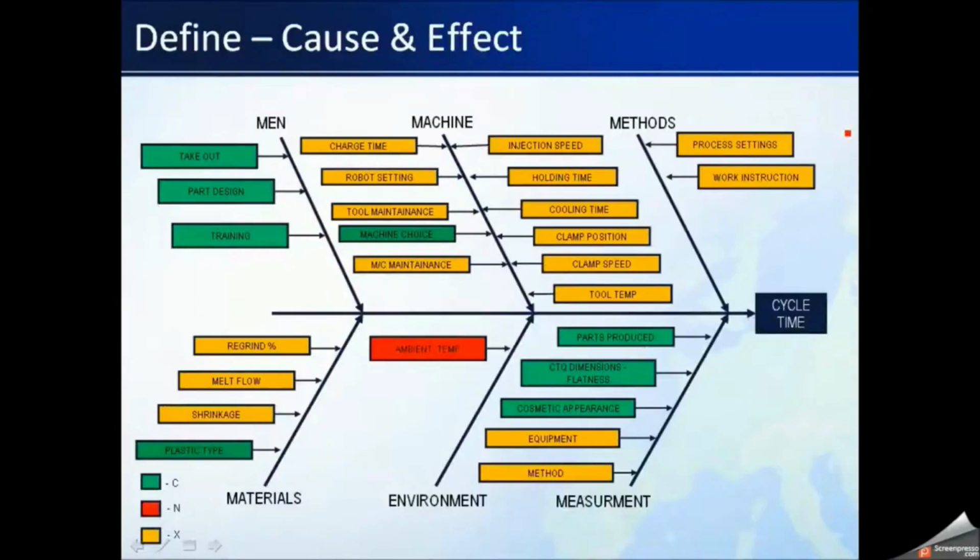So let's go back to those variables. Now the first thing they have to do in order to be able to interrogate the machine and find best settings, because here is where we need to find best settings. So these things, injection speed, holding time, cooling time, etc., tool temperatures, all of those kinds of fine settings, the only way to find best settings that work is first of all to establish a controlled environment into which those settings will be used.